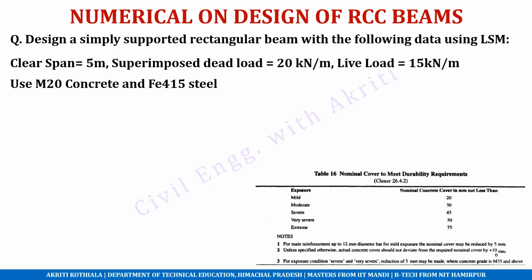Now let's start with a numerical problem. Design a simply supported rectangular beam with the following data using LSM. LSM is limit state method. The clear span is 5 meters. Superimposed dead load is 20 kilonewton per meter. Live load is 15 kilonewton per meter. We've been advised to use M20 concrete and Fe415 steel.